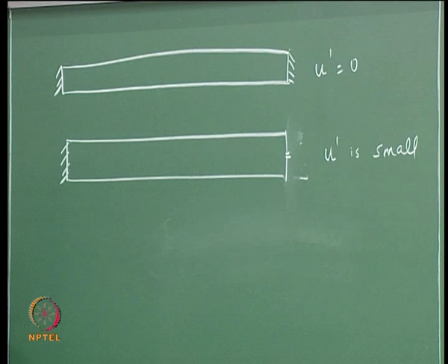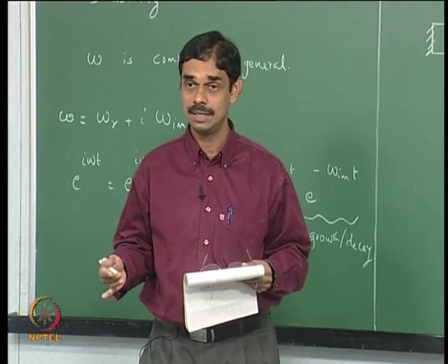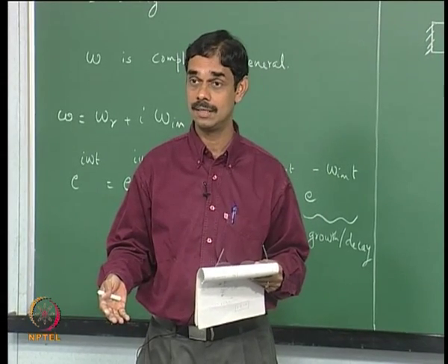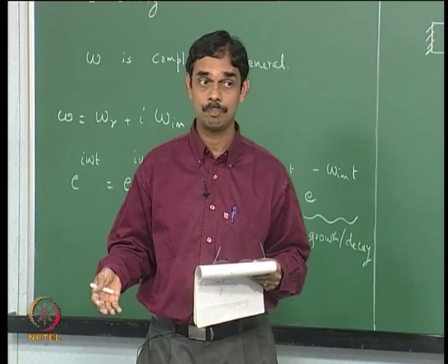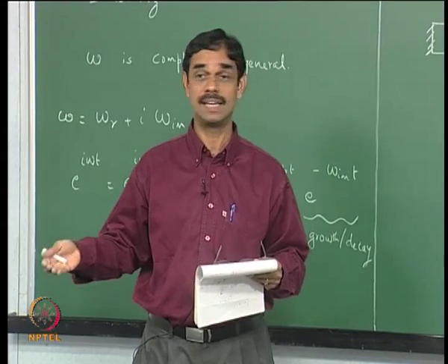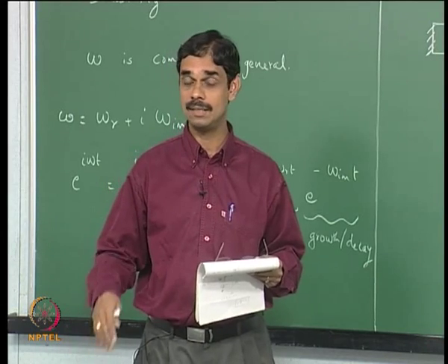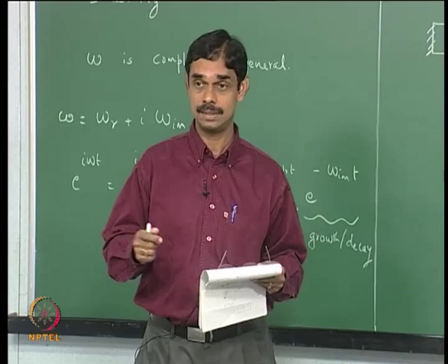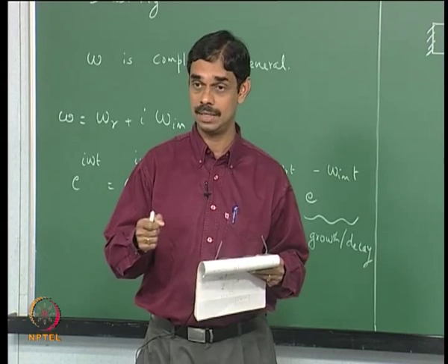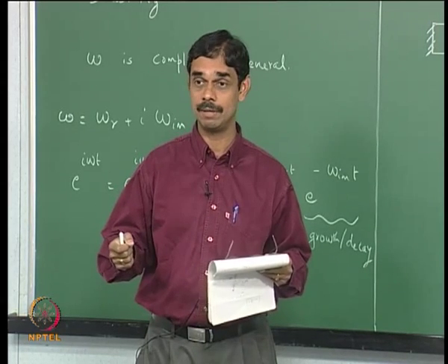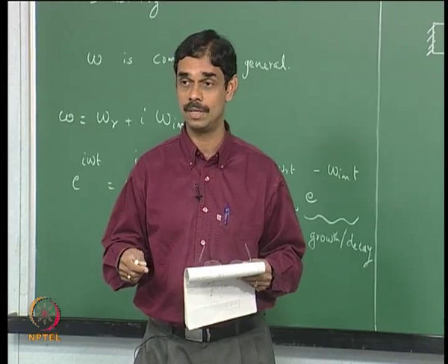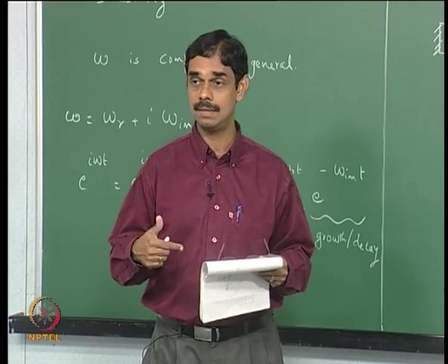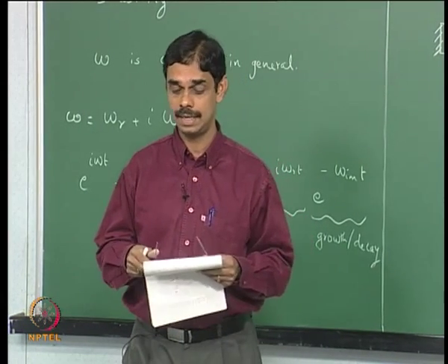Okay. So we need a solution, and we have the solution for pressure, which is a e power ikx plus b e power minus ikx, and we know by now how to get the expression for acoustic velocity, or the particle velocity, by using the linearized momentum equation for small perturbation. So you get the velocity and then apply the appropriate boundary conditions, right?